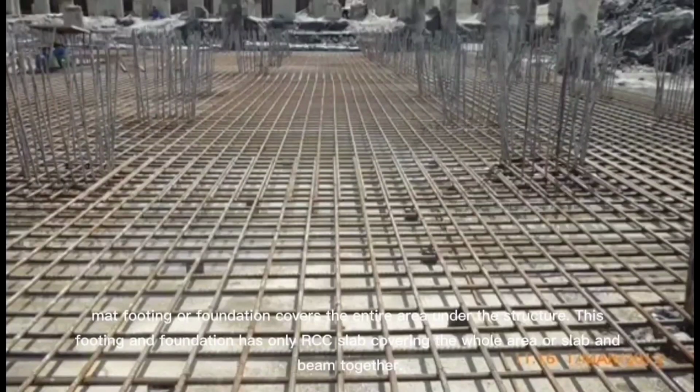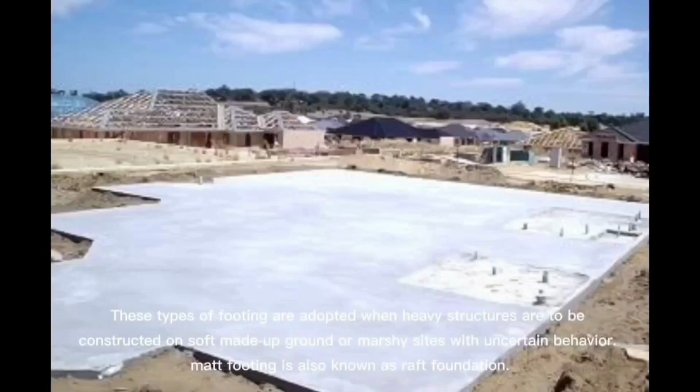Mat footing or foundation covers the entire area under the structure. This footing and foundation has only RCC slab covering the whole area or slab and beam together. These types of footing are adopted when heavy structures are to be constructed on soft made-up ground or marshy sites with uncertain behavior. Mat footing is also known as raft foundation.